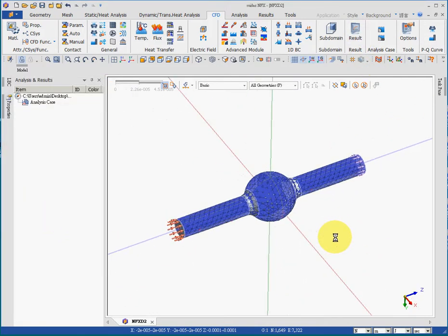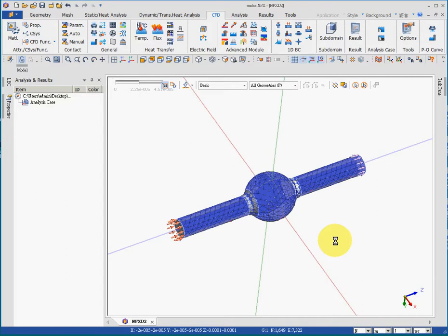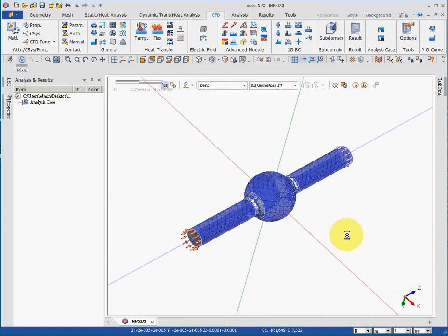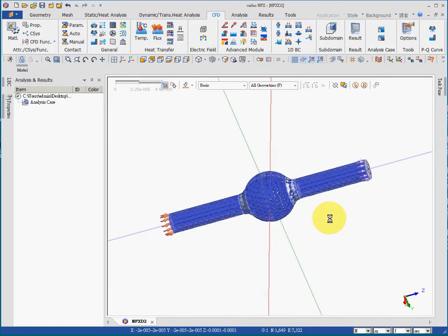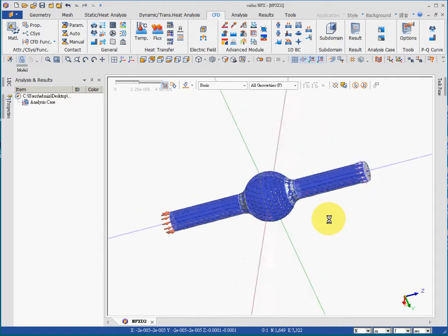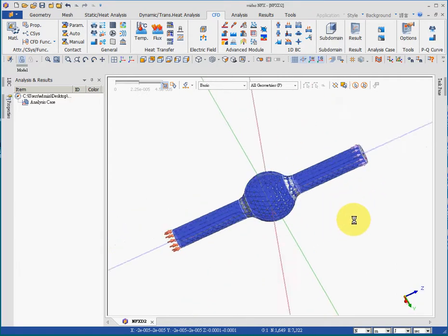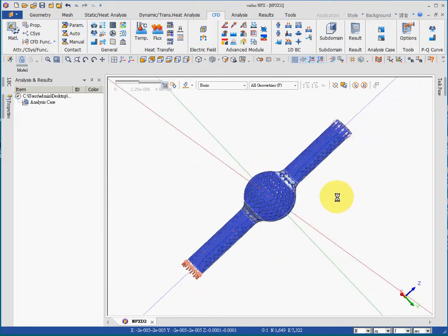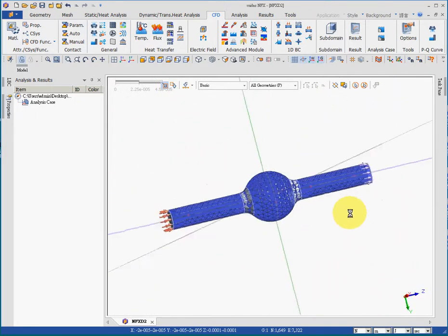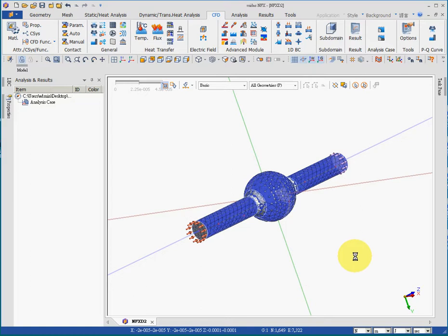Actually, for example, in SolidWorks Flow Simulation, it is called goals, and in ANSYS Fluent, it is called monitors. So we need to tell the computer or the software what we are interested in, or we want to measure something, and at this point or this quantity, the software will calculate the iterations until the error reaches a predetermined value. So this is the step that we need to do in CFD, where in solid mechanics we do not have.